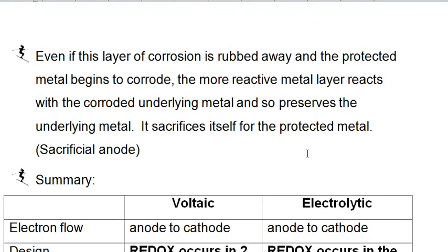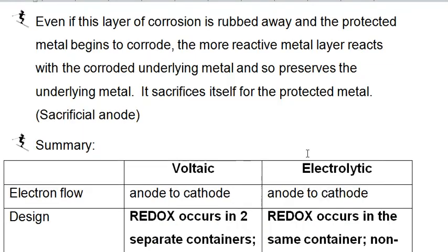And then silver tarnishes. Silver does tarnish, but again, that tarnish doesn't wipe off. It's like with iron, we've all seen it. When it rusts, it's crumbling, it flakes off, and then it exposes more iron. But with all these other metals, when they corrode, they form an oxide layer that sticks. It doesn't flake off. As soon as that oxide layer is there, it locks out the environment, and doesn't allow any more corrosion to occur. So silver's the same thing. It'll tarnish, but that silver tarnish now acts as a barrier between the underlying silver and the environment. You don't get any more reaction. It's almost like plasticizing it, right?